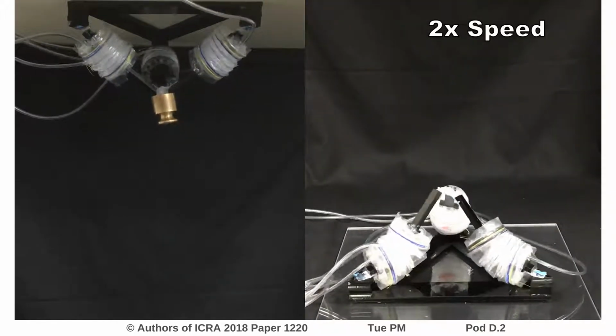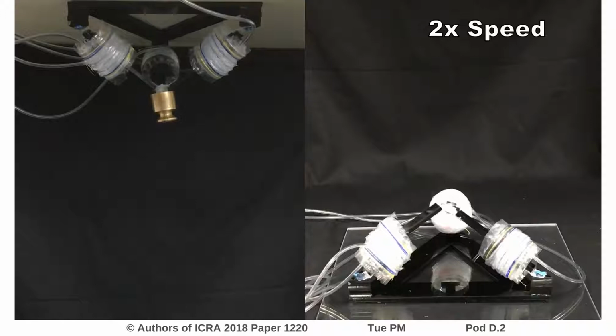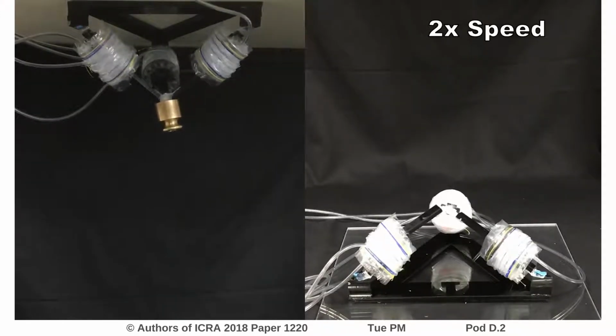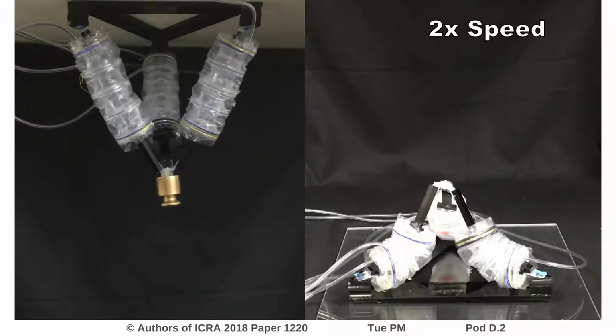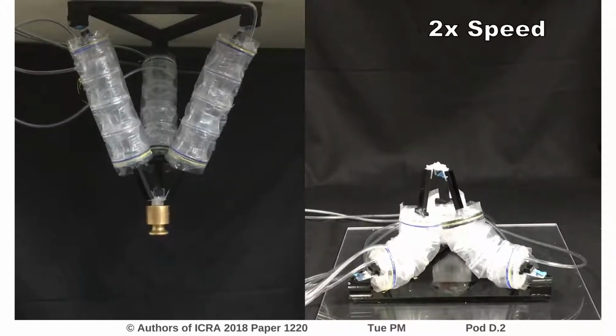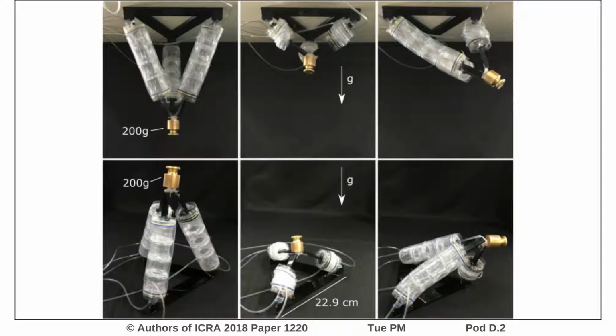In these videos, actuator speed is limited because pressures are controlled manually. In general, the speed of the actuator is limited by flow rate into the actuator chambers. Future work will analyze these actuators in buckling and bending. These actuators are fabricated from acrylic discs and low-density polyethylene tubing.